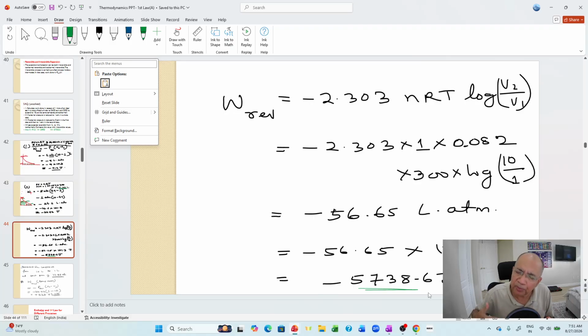So more the number of steps, more is the work done. Supposing 24.83 atmosphere to first 20 atmosphere, then 20 to 15, 15 to 10, 10 to 5, 5 to 1, the rectangles would have been more, bigger and smaller. So if you add, this addition will be very close to, not equal to, the area bound by the curve. So this numerical, we have to do it.